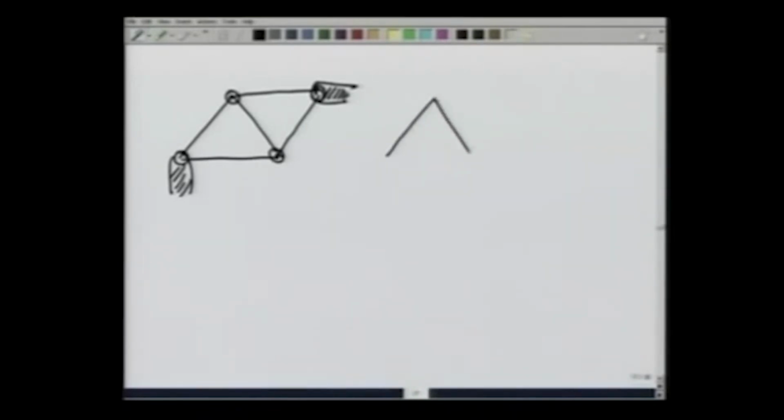Another way is I have this basic truss which is fixed here, I do not want to fix it here now. I provide one more member, so that this point now has 3 members that can provide equilibrium to it. This is a fixed point, and suppose I want to put this under a fixed point. Then this member has one force coming from the fixed support, one from this member. So, I have to provide one more member, so that there are 3 forces acting on it. But this gives a loose end here. I could fix this loose end by putting 2 members here.